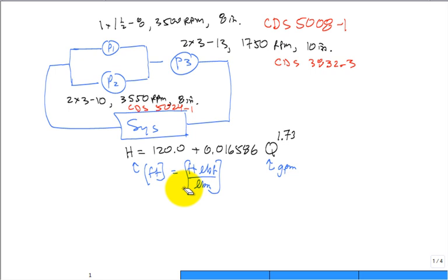True? Okay. So if you plotted this, what does this plus sign make the curve for the system head look like on a plot? Something that starts at 0, well, it doesn't start at 0, does it? No, it starts at 120. And then it has a quadratic nature to it. It's close to quadratic. The coefficient is about 2 on Q. That's our system.